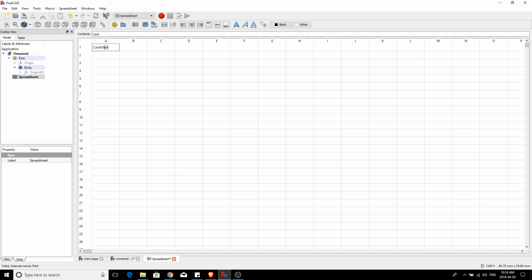So this is basically how long the credit card is. Now I measured earlier using a set of calipers, and my credit card is about 80 millimeters wide. There we go. So you can imagine the next thing we're going to plug into here is probably the Y height. And I believe that was about 48 millimeters, just like that.